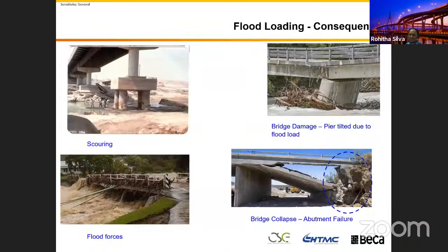One reason is I couldn't find proper detailing in the Euro standard as well. In the Australian standard, especially after the 2011 flood in Queensland, when they revised this Australian standard in 2017, I think the flood loading section had a significant improvement, and it incorporates so many things. It's quite comprehensive as well. If you do not have a code to design for flood, I suggest you refer to this code.